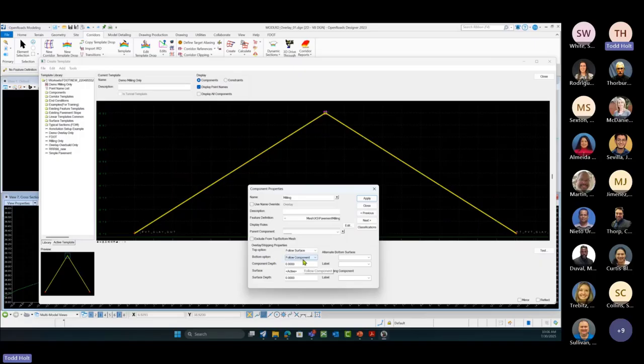the component. So if I had a certain depth that I wanted the bottom option to set, or a minimum, I would come in here and set this minimum depth of, say, 4 inches or 3 inches. So if I have that minimum depth in there. So again, if we think about that pavement design, what are we doing in that pavement design of mill and fill, right?